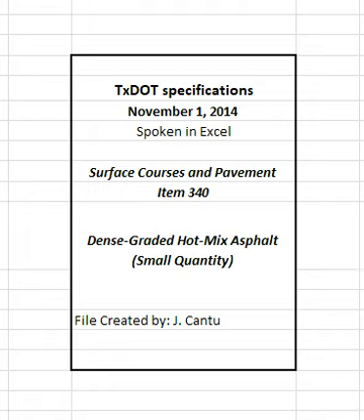4.4.1 Storage and heating of materials. Do not heat the asphalt binder above the temperatures specified in Item 300, Asphalts, Oils, and Emulsions, or outside the manufacturer's recommended values. Provide the engineer with daily records of asphalt binder and hot mix asphalt discharge temperatures, in legible and discernible increments, in accordance with Item 320, Equipment for Asphalt Concrete Pavement, unless otherwise directed. Do not store mixture for a period long enough to affect the quality of the mixture, nor in any case longer than 12 HR unless otherwise approved.